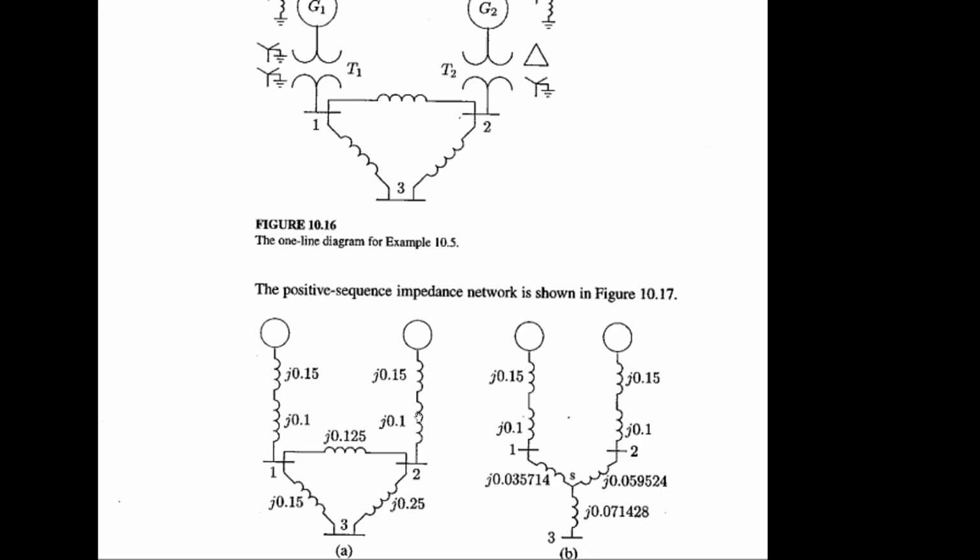This part you can see is the simple single line diagram, right? It is for the regular or positive sequence. So what you have solved on the three-phase concept is applicable for positive sequence calculation only. And like the earlier scenario, when you want to solve the impedance matrix determination, that is the positive sequence impedance matrix only.